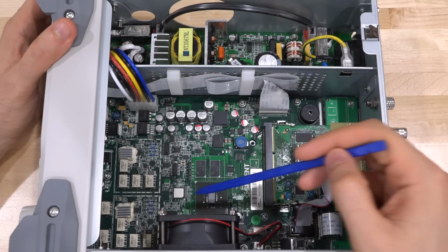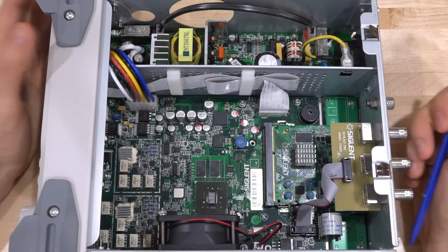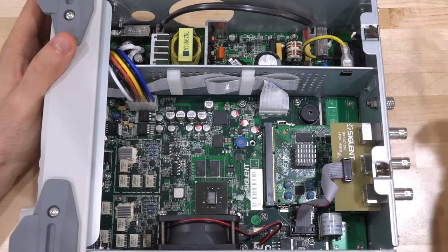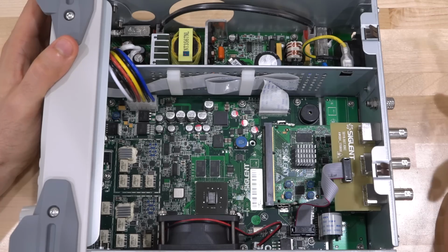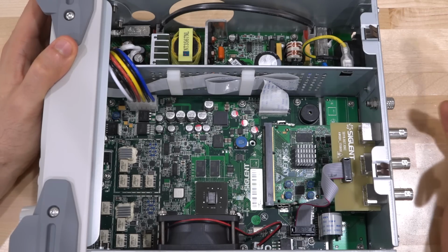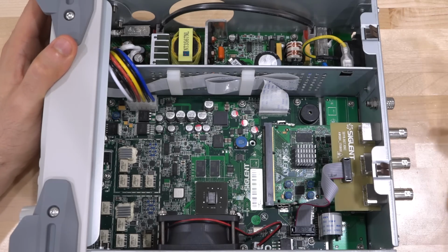There's a lot of stuff happening here. Now, we know this is a 2-channel arbitrary waveform generator, so there are some things we expect to find. Amplifiers for each channel, circuitry for doing the different level amplitude control, PLLs and DACs and FPGAs and memories. So we're going to go and see if we can find all of those components.